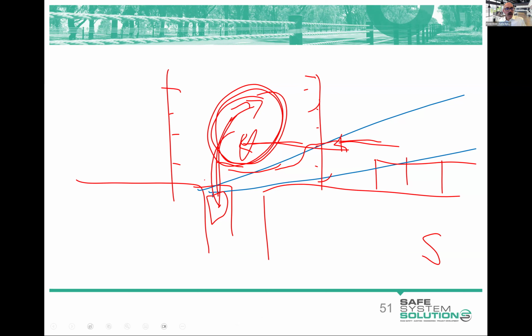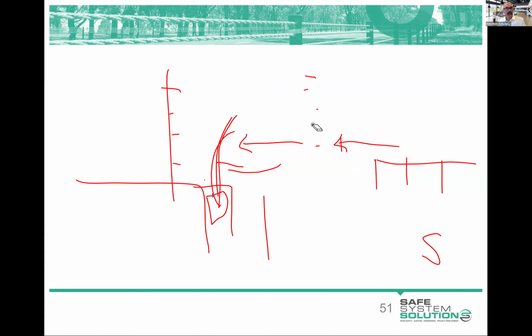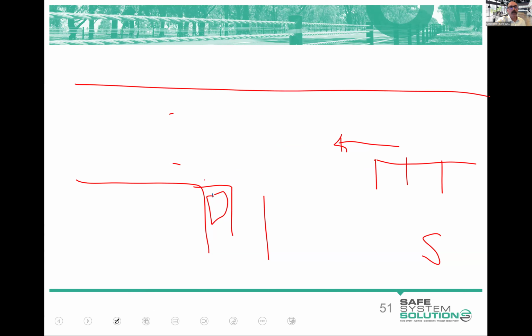Some people would often also want to say that signalizing this would be a primary treatment, but it is not. It's a supporting treatment. So, okay, you're going to spend a lot of money to signalize it. We call it a supporting treatment still. Why do we call it a supporting treatment? Well, it's probably one of the higher effectiveness supporting treatments.